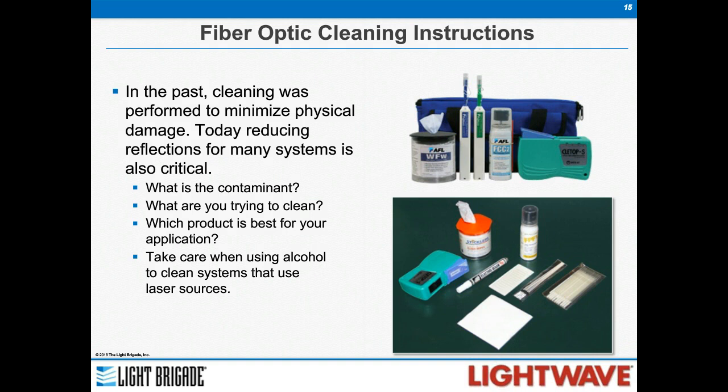And take care using alcohol. You want pure alcohol if you use it at all. You're better off with a cleaner that is designed for fiber optics because they do leave a residue. You want to do a dry wipe after you do a wet clean if you have oils to remove, because that residue will affect your reflections. So make sure that you follow up a wet clean with a dry wipe.